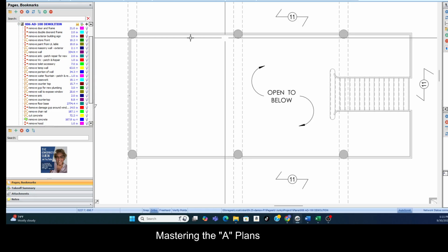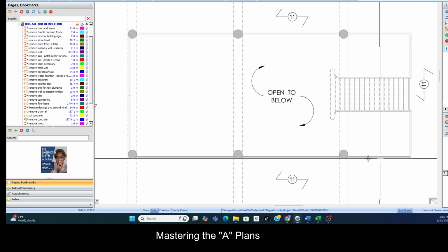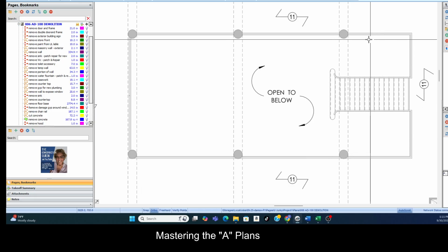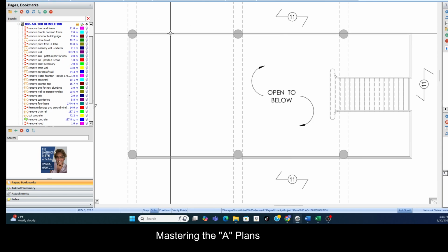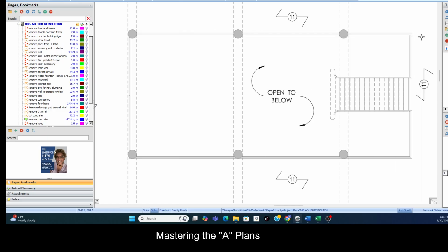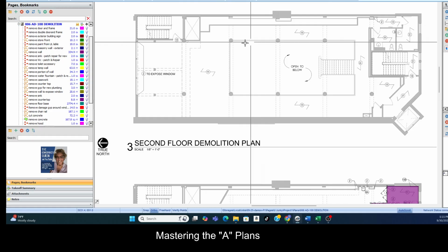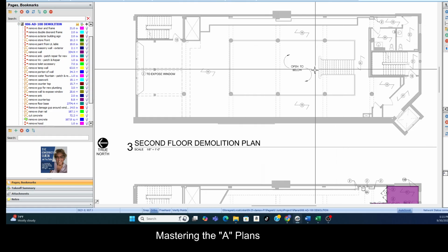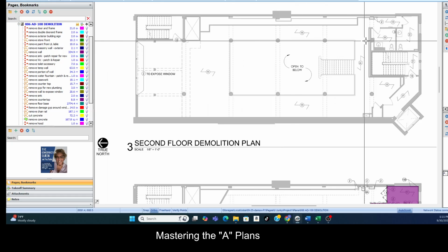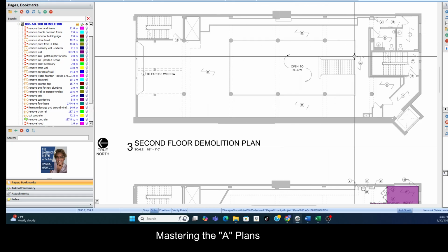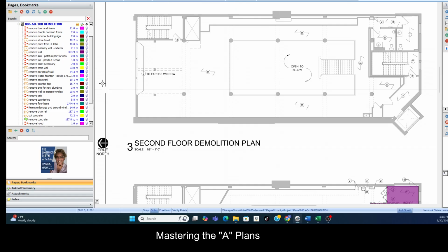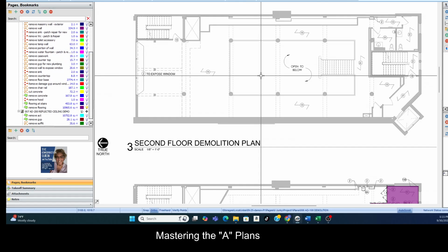And I'm assuming that this is like railing, right? Not wall. So I didn't calculate any wall base along here. I'm assuming because it's open from below. Usually that's railing, so verify that there is no wall base around there, and we've got to change our number for our demo floor. Removed. Now let's redo that.